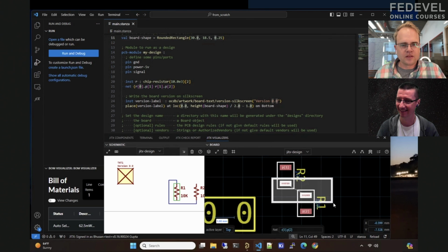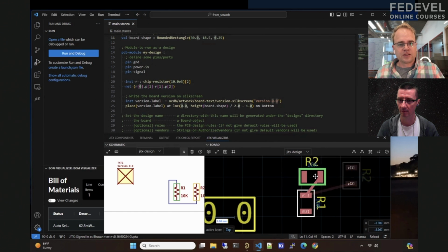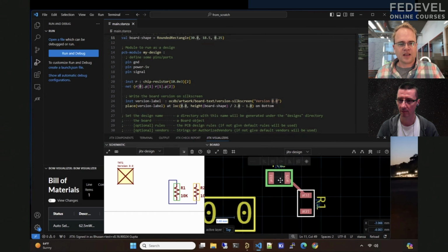So we have a new type of router in here. It's an auto router, in that you're not going to draw the exact path. Well, you can draw the exact path. But the way it works is you select a layer and a set of pins, and then it will route them. Okay. So like this, and I just press Q, which is route, and now I have a trace. And this trace is following all the rules of my stack up. I can't really get it to bend around interesting things here.